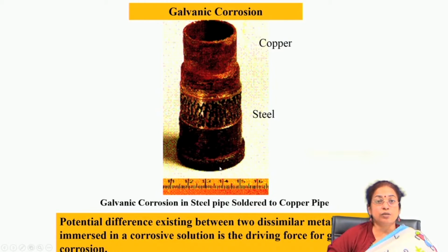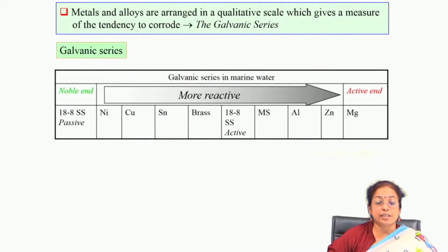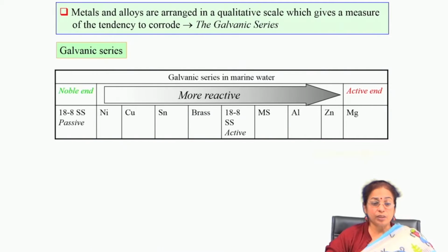So, galvanic corrosion can be a dangerous form of corrosion which starts at the interface and then proceeds to a large extent towards the other side of the component, and it is naturally a kind of localized corrosion. In many cases it occurs not only in dissimilar combinations, but also when a metal has dissimilar phases. Depending on the corrosion probability or EMF of the individual phases, there may be micro galvanic cell formation, as a result of which galvanic corrosion proceeds.